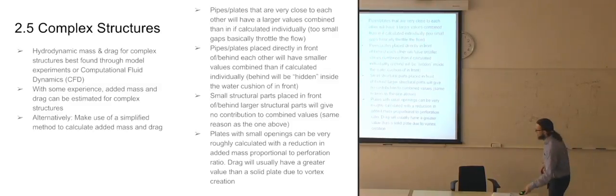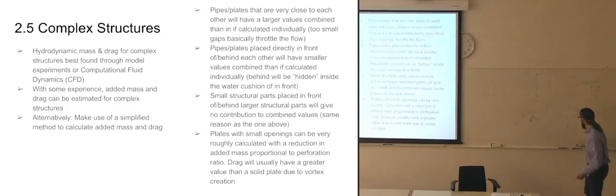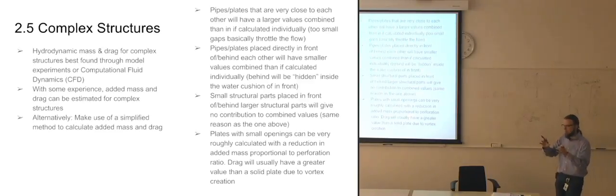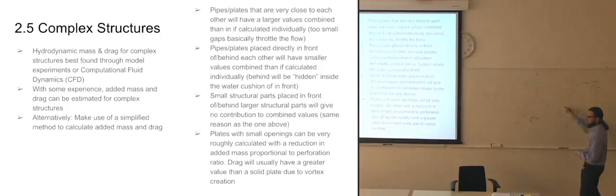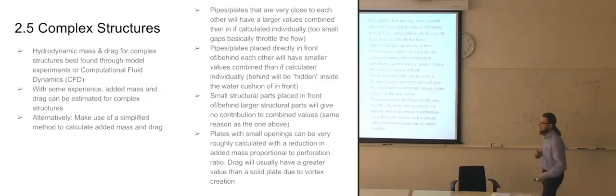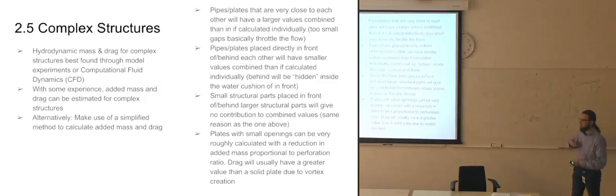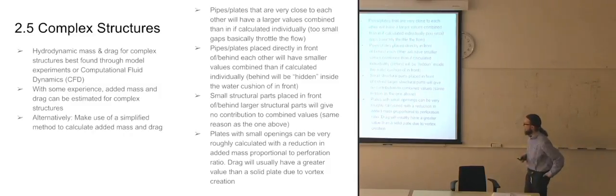So basically, the perforation ratio will be looking at how much area we have lost through the holes. So all of the holes combined, how much area is that? And then look at the area that is left. So then look at the total area, because then you will get a ratio between them. How much has been hollowed out and how much is still there.